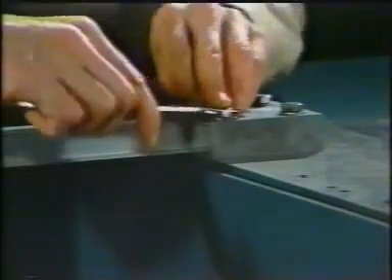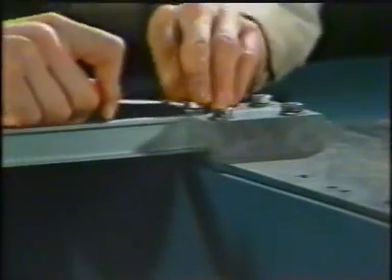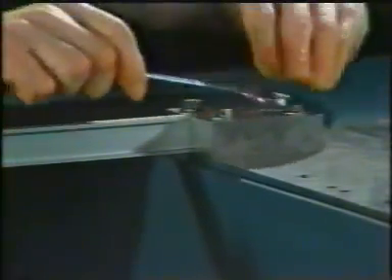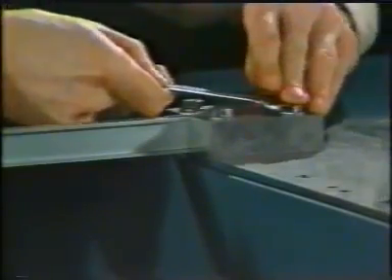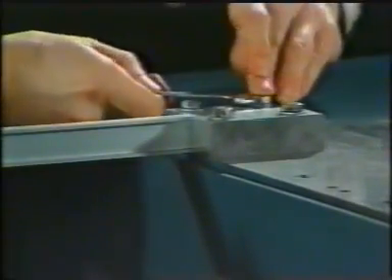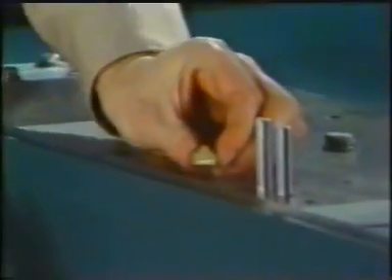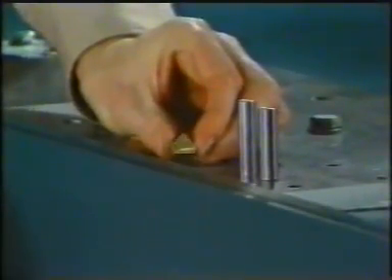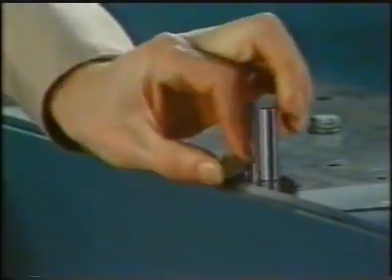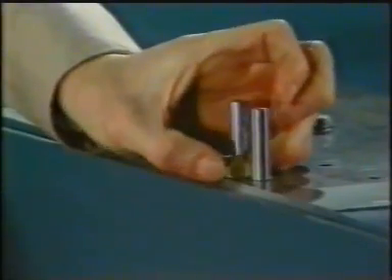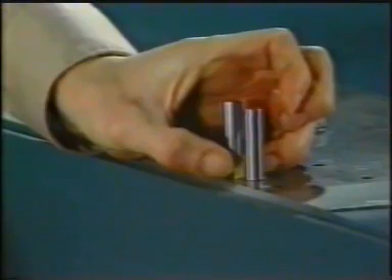So far, little has been said about the end conditions of the beams. As with columns, the end conditions have a considerable influence on the stability of the member. This support is fully fixed and restrains all component distortions, whilst the one on the right is a simple support which permits rotations in both the vertical and the horizontal planes.